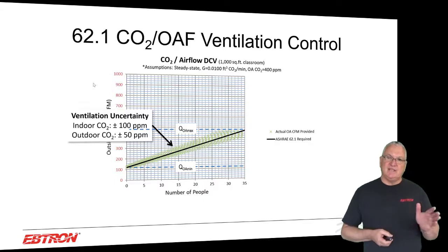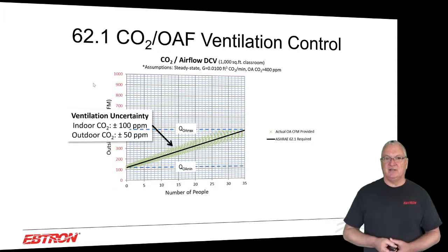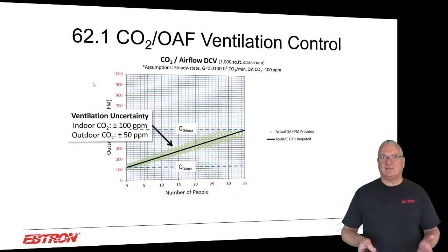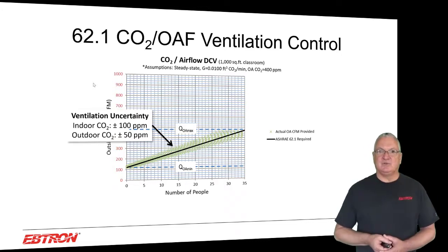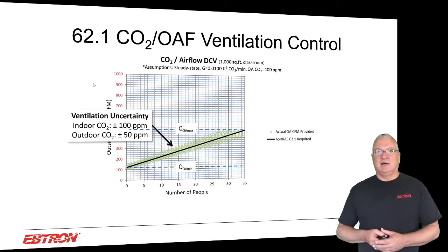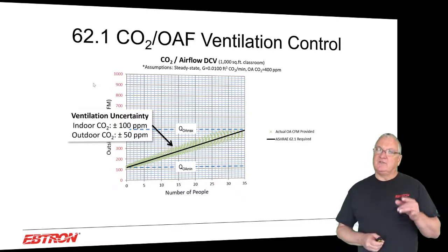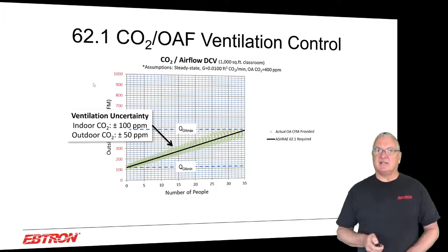Now, in everything I just showed you with DCV, I don't know if you realize this or not, but right now we have a problem with DCV and lowering ventilation. We want to maximize ventilation. You've already got everything you need. You have an outdoor airflow meter, whether you're doing this fixed set point CO2 method or the population based method, and all you would do is set the outdoor air set point to whatever the maximum you wanted, and that's what you maintain. You'd be done. You could flip from this normal energy saving mode to basically pandemic mode immediately. That's not easy to do for the systems that simply rely on CO2 levels that you have out there today.